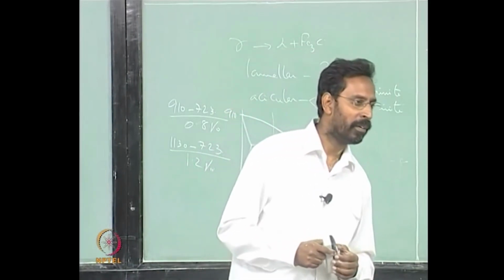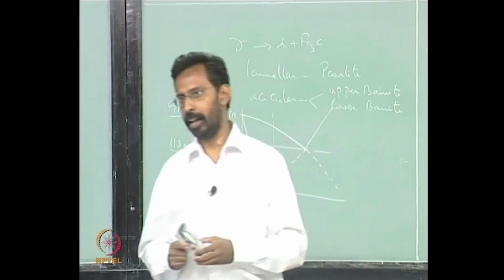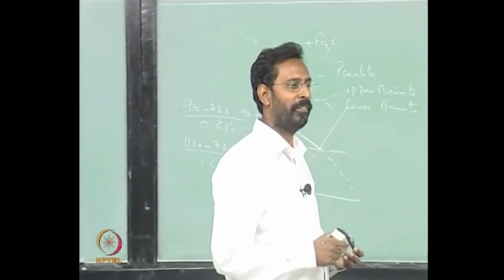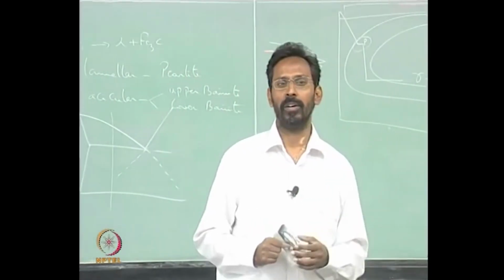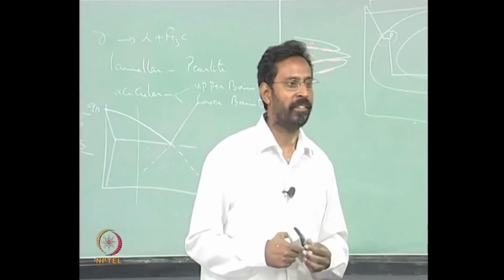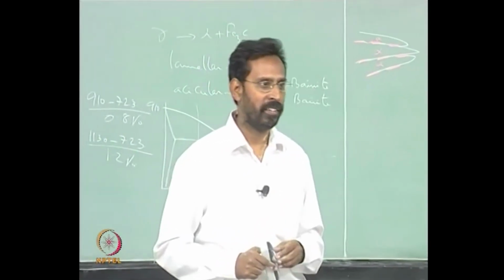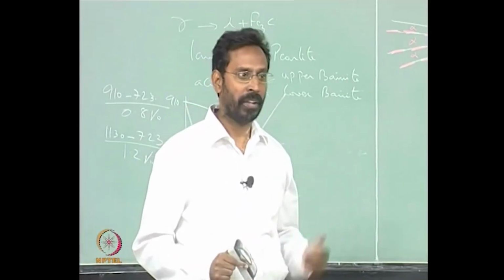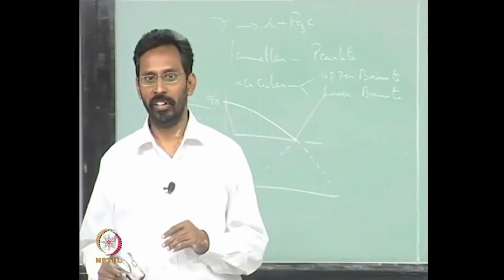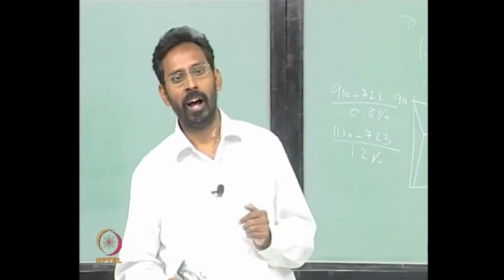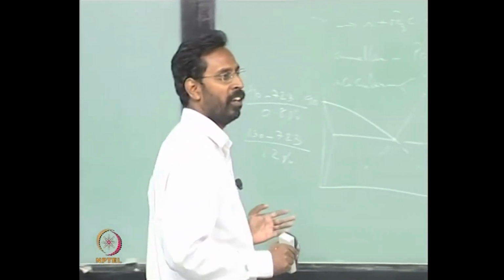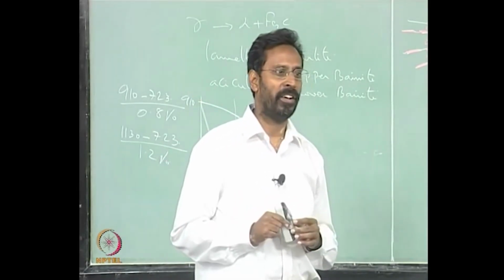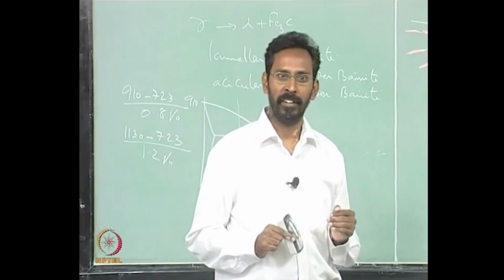but still there is a problem: coarse grained strength decreases, fine, toughness decreases, okay. One more, you get more quench cracks when you are quenching to get martensite, because you are quenching from a higher temperature, thermal shocks are more. So that is the reason why, in tool steels, there is a possibility of quench cracks. That is the reason why tool steels you do not quench them hard. Luckily because the carbon is higher, the hardenability is higher already.